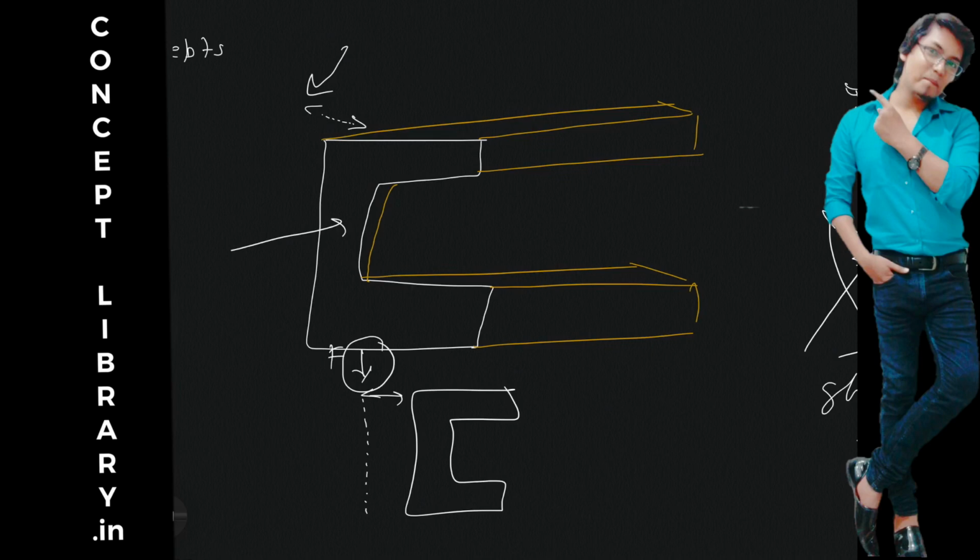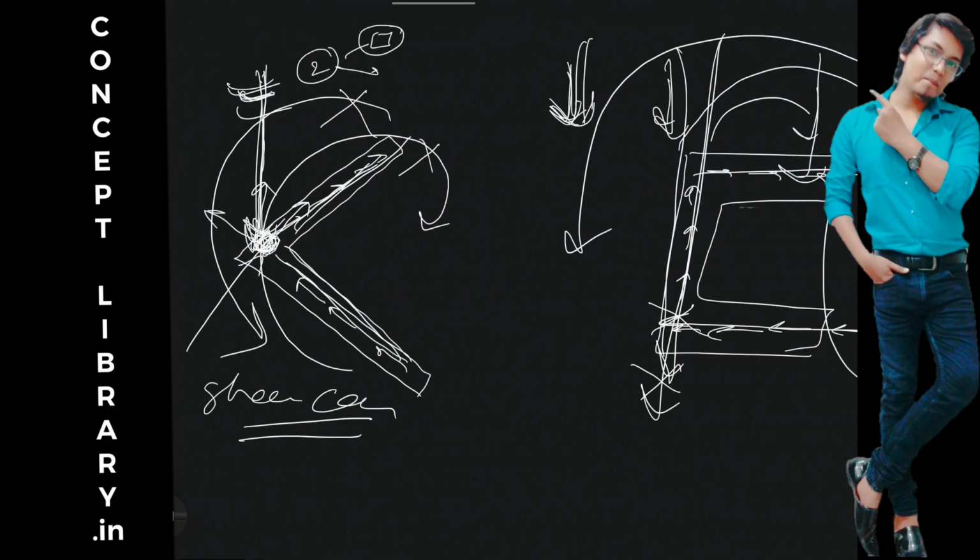And now where will be your shear center? You draw one symmetric line which will divide this body equally into symmetrical bodies, okay? I mean this body is symmetrical about this axis, correct? So draw one axis line. So this point will be your shear center, like the action of this force and this point. I hope you are being clear, okay?